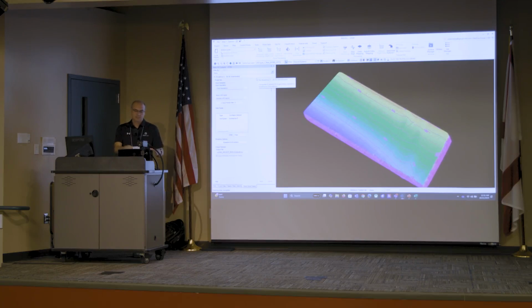I just put these LAS files into another engineering software, you're going to probably have some problems in terms of performance. So what they do is a ground thinning to remove a little bit the amount of points that we have on the ground before exporting to, let's say, Civil 3D or any other CAD solution that they have. So for that we have this option here, the ground thinning, right? So you can reduce the number of points per square meter before sending to the engineering software.